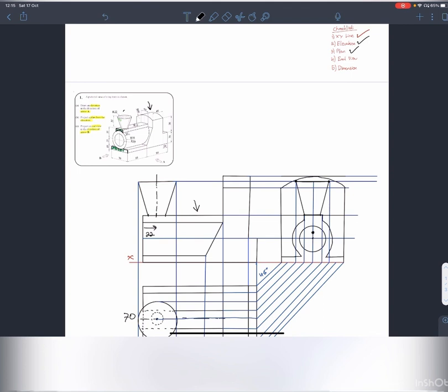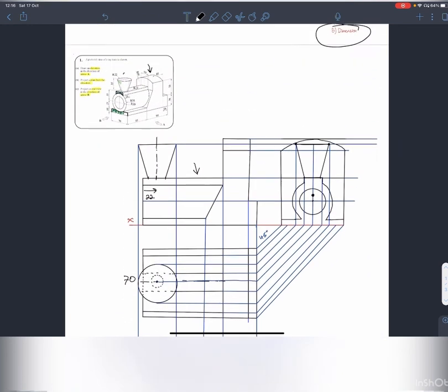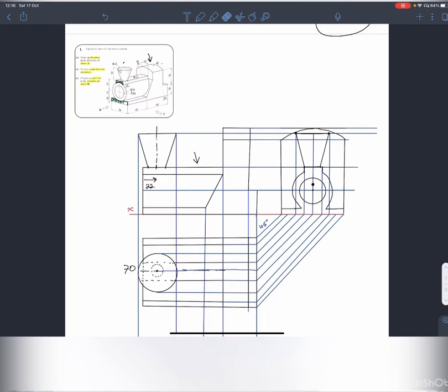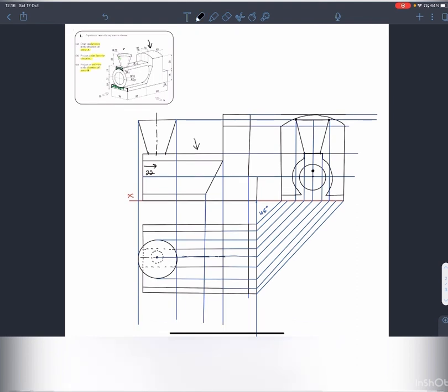So I have the end view complete. I just need to do dimensions. Okay, so dimensions are fairly easy. We've already covered them. All you need to do is pick dimensions that you add in yourself. Okay, so we can pick the 70 here. We'll add in 2 dimensions for you. We can pick the 70 mark, so we'll have 70 here. We'll draw in our dimension line, arrow, arrow, and 70.